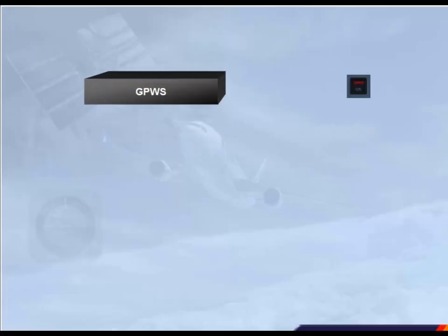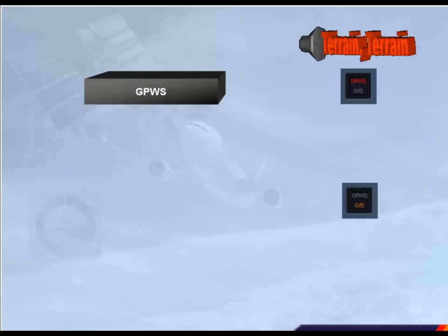The A330 family is equipped with a Ground Proximity Warning System, GPWS. Its purpose is to enhance safety by alerting the crew to potentially hazardous situations involving terrain collision or incorrect landing configuration. The GPWS monitors the aircraft flight path and generates visual and audio warnings alerts when the aircraft is in one of the defined hazardous situations. These warnings will be overridden by stall or wind shear warnings.